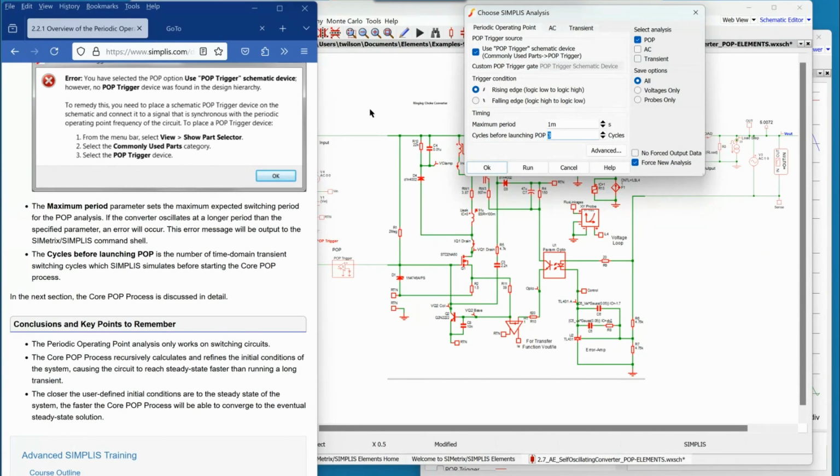Yeah, that's a very good point. So 3 is actually a very small number, and after the break you'll see why we picked 3. First of all, we use this in the training class all the time. We know the circuit and we know how to initialize it, so it can converge nicely with 3. Also, the dynamic range of this circuit is very narrow. It just doesn't work very well. This circuit was very popular when cheap trumped everything, so being a cheap circuit was better than being an efficient circuit.